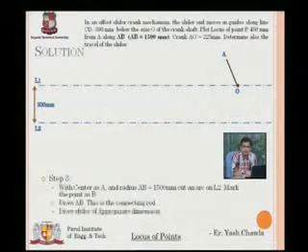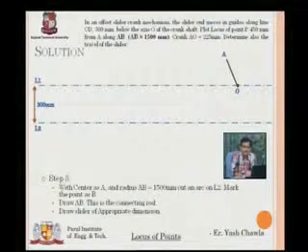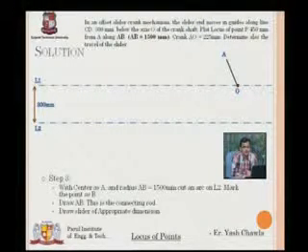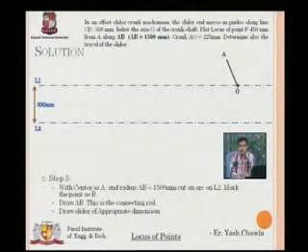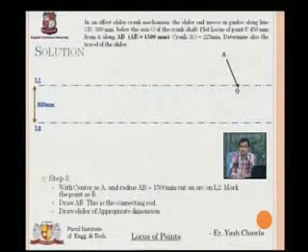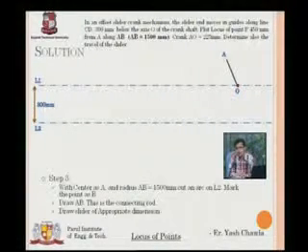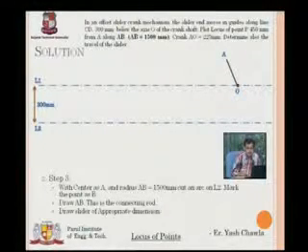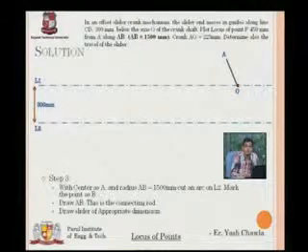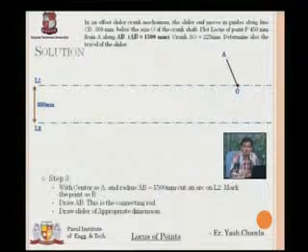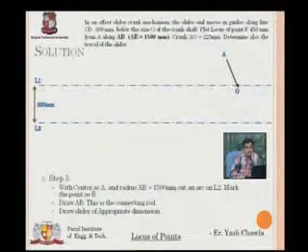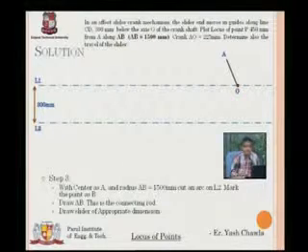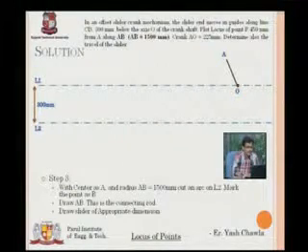Now the next step, what will be my next step? With center as A, as we did in the previous question. I have my position of A. Now for that I need my position of the slider. For that I need to know where the initial point and the final point of the connecting rod will be, because A will be the initial point of the connecting rod, that we know. The final point of the connecting rod will be connected to the center of the slider. So if I have the length of the connecting rod from A, and the path of the slider, I will have the slider position.